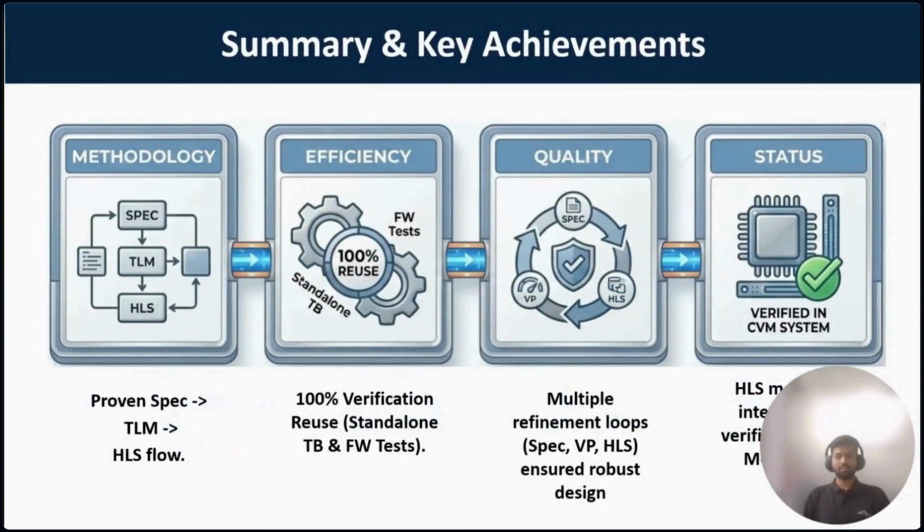To wrap up, here's a quick summary of what we have achieved. Firstly, we successfully took the design from functional spec through to a full HLS implementation. Using this flow allowed us to refine the architecture early on. A major benefit was verification reuse. We were able to use the same test bench and firmware test across every phase, which saved a lot of time and kept the testing consistent.